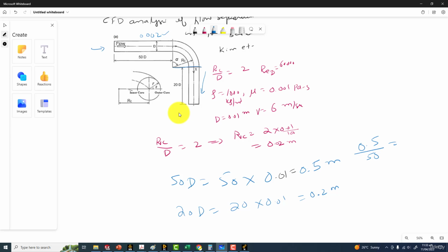And on the bend, we need to have a very fine mesh in this region, because the 3D flow will be here along with the separation. So I need to provide some sphere of influence. Maybe 2 will do the job, one on this side and one on this side. And the sizing, I have decided here, should be around 0.0007 for the coarse mesh.